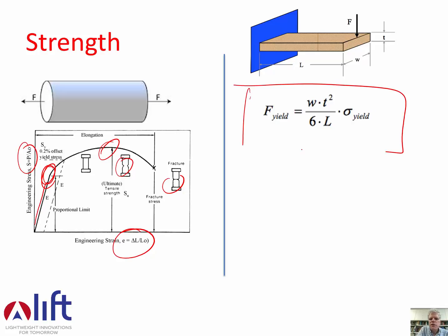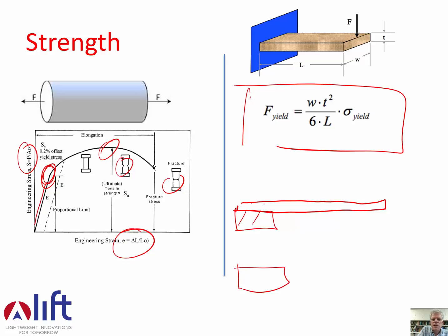And again, just by measuring the force at which it yields. And how do you know it yields? Well, when it yields, you start with a nice straight bar that might be attached to a table here. If you take that thing and reach the yield load, you'll absolutely know it. It will bend like that, and it won't come back. You've all seen that when bending paper clips and so forth. When it doesn't come back, you've hit the yield force.